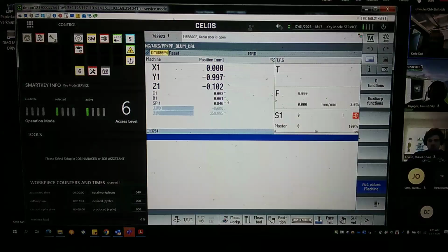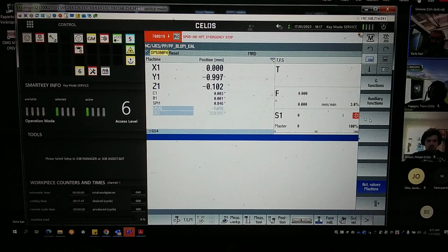Okay. Also in the frame underneath, in the third frame, you see here S1, that's the main spindle. Also the first value is the actual speed. And also here in the right down corner, you see the percentage value of override. Remember, here we don't have a potentiometer. Here we have buttons, arranged in the middle section of keys in the machine control panel.